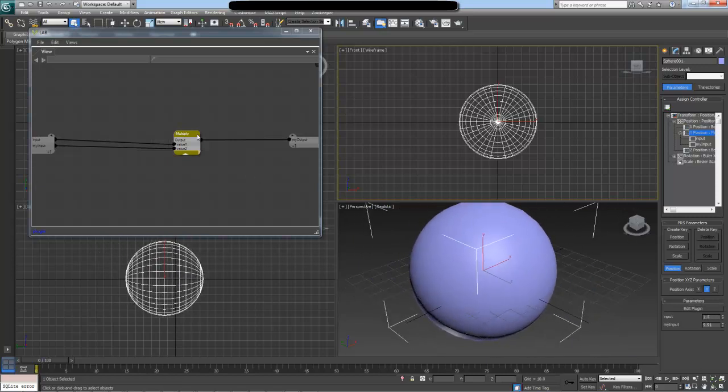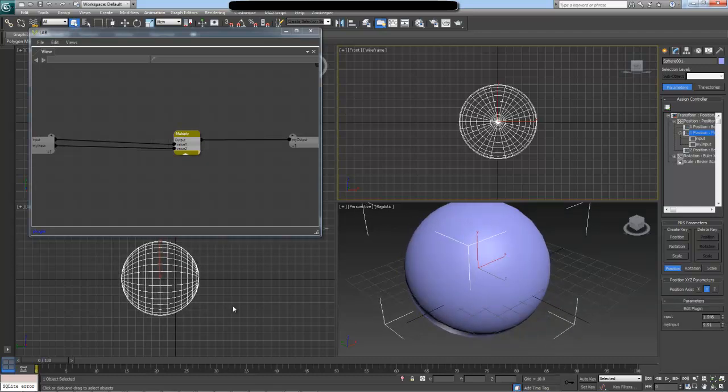And just to make things even more interesting, as opposed to letting the user control the Y coordinate, let's have time drive it. 3ds Max has the time slider here, and as I move the slider, this changes the scene's time. And let's actually try to get the lab to use the time of the scene to specify the Y coordinate of the sphere.